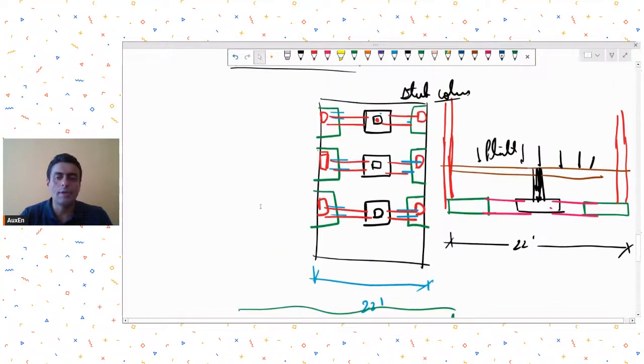Maybe they won't be comfortable with that tie beam, or at worst, they will change and appoint another structural engineer. So because of this situation, I suggested it is better to have an internal column and just provide a stub column and small tie beams. This is more acceptable purely from the viewpoint of the client, what he or she thinks.